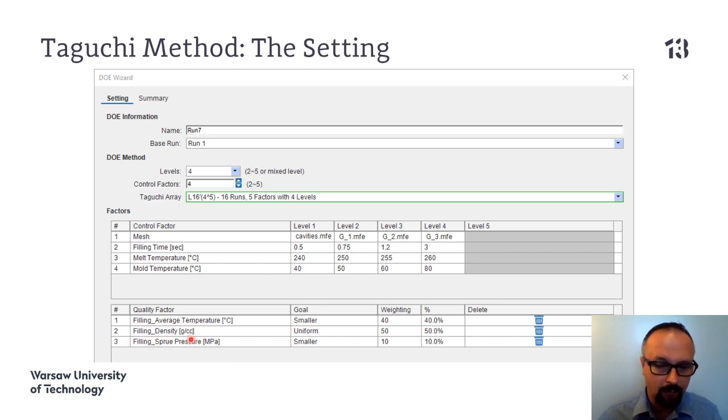And in this case, we decided to assess our mold filling imbalance by the value of standard deviation of the distribution of our density at the end of filling stage. Because as we can imagine, if some cavities fill faster than the other ones, they reach the packing stage earlier, and the density of these cavities, the areas which are inside these cavities, is getting larger.